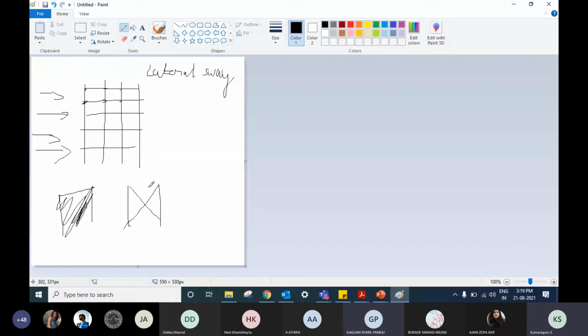So there's an increasing order of lateral stability that each thing provides. In ascending order, the first thing is your moment connection, or rigid frame connection, the moment frame, which is effective up to a certain point. That is why, in tall building methodology, you would see a simple moment frame go for about 10 stories or 20 stories tall, right? Beyond which, this can reduce the lateral sway, but only up to a certain story height, around 20 stories or so.